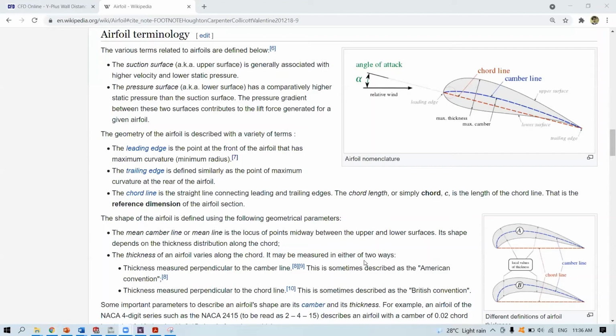Welcome to part 2. Before going further, I should take a minute or two to focus on the definition of the leading and trailing edge, just so that we are on the same page. Identifying the leading and trailing edge will be important to later separate the F1 into having the upper surface as well as the lower surface. This will not only assist in designing the guide curves, but also in post-processing, where we may need to extract the CP and CF values for either surface.